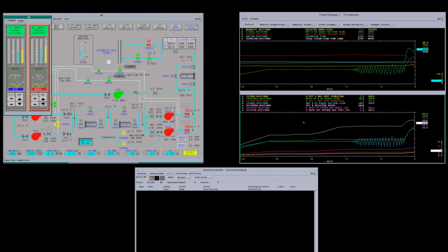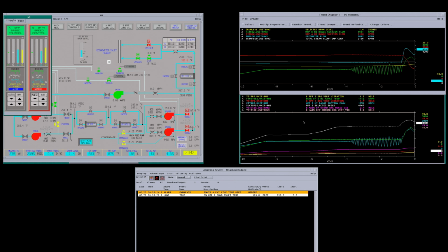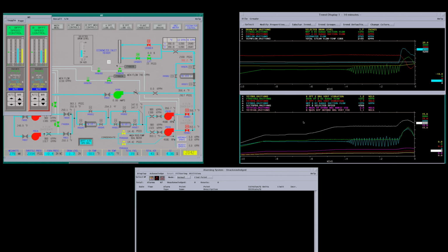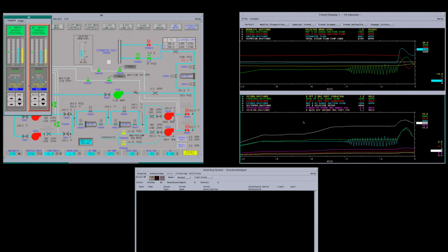This boiler uses the feed pump speed to control drum level. It'll jump a little bit. There's no level control valves on this. That's all done with feed pump speed. So the feed pumps will line out. We didn't swing the drum too much. Right now we're 2 inches high.